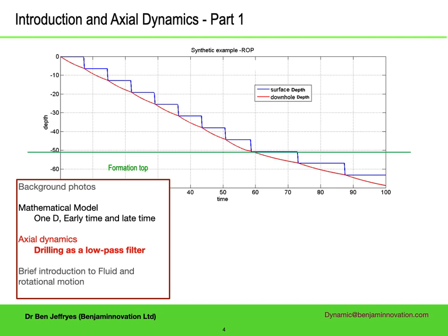The late-time axial drilling dynamics looks like a one-pole low-pass filtered version of the surface motion. In the picture you see modelled the motion of the top and bottom of the drill string. I also introduce the dynamics of the fluid and the rotational motion.